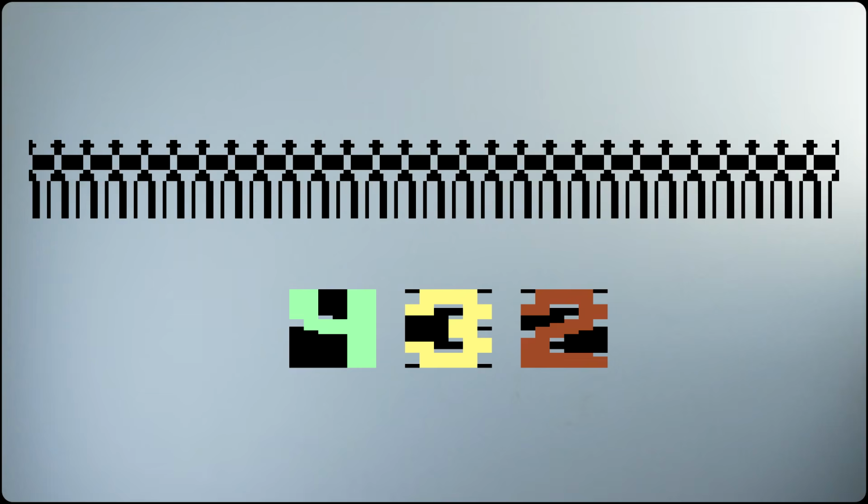But we can change the contents of this memory location occasionally as we go. And that's also part of the device. So while the video chip is rendering these 2 sprites in the upper border area, the CPU is executing timed code to update the ghost byte to get a different repeating pattern on each raster line. And now watch very closely what happens when I move the repeating ghost byte pattern underneath the blocky sprite graphics.